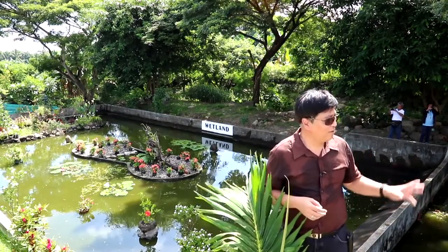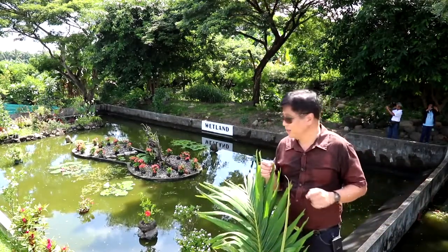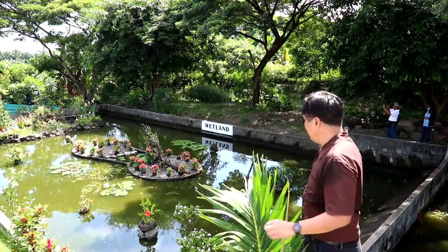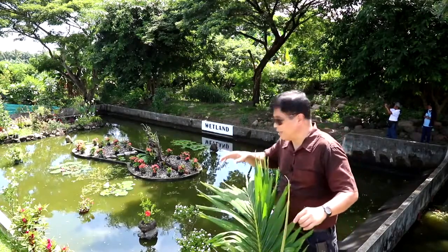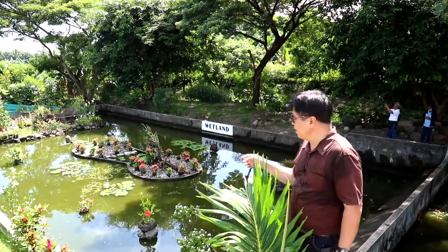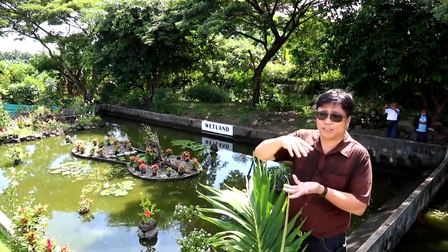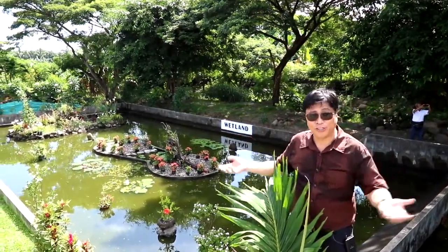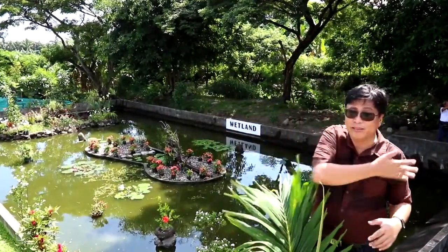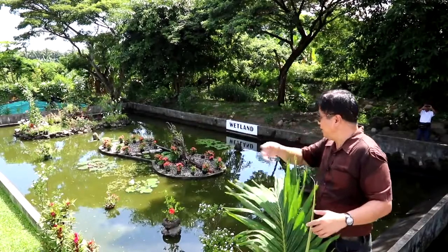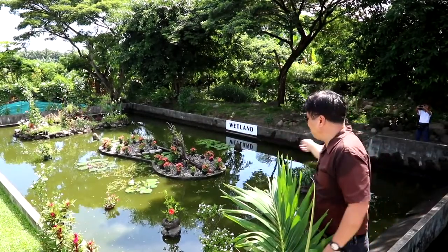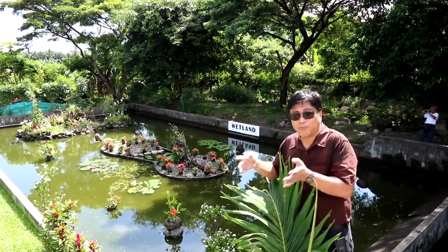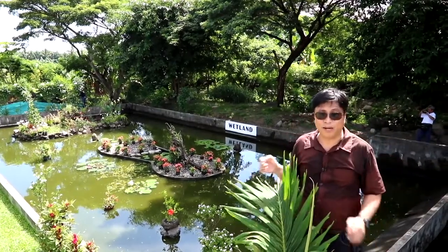The overflow from the gravel filter goes to the wetland. This wetland simulates the natural environment of a pond, where there's also a liquid component on top of the surface. This also serves like an unaerated pond, no aeration, but because it is very shallow, the wind action causes introduction of oxygen. They intentionally made it beautiful and put landscaping around the area. And this also cleans further the liquid already filtered from the planted gravel filter.